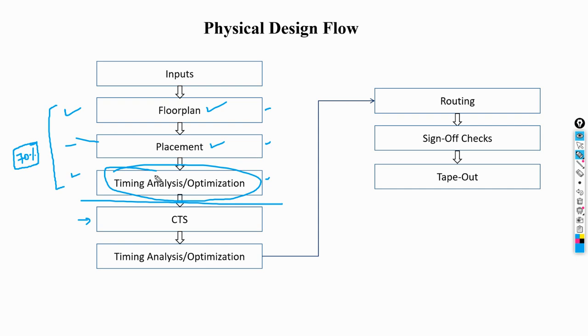You guys know that, and you might have heard of, I'm not saying you might have learned in your textbooks, setup time and hold time and all of that. So you would have to perform setup check here. Hold we will not be doing before CTS, and we will not discuss why we don't do hold before CTS right now. CTS also will have different goals. Mainly we have something called insertion delay, and you will also have something called skew. These two are the main things in CTS, and there is a little more in depth. When we get into CTS, we will discuss in detail.